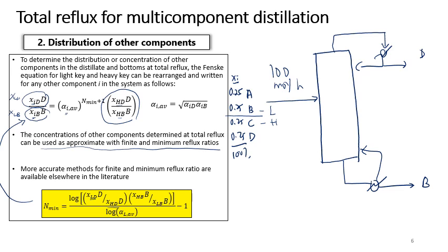If you specify to have 90% of B recovered in the distillate product, so meaning in the distillate product here, you have component A and component B. And initially you will estimate 100% of A will be recovered in the top product, meaning 25 mole of A will be here. And then only 90% of B will be here. So what happened to the C and D?